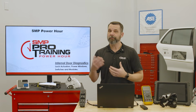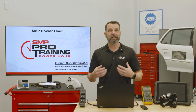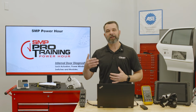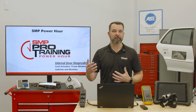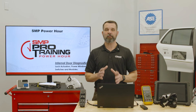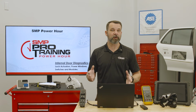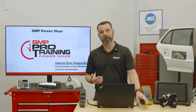And so in summary, modern vehicles rely on a network of switches, motors, and modules, and the BCM to operate something as simple as a window or a door lock. And when we're diagnosing these systems, we need to think logically. Did the BCM get the command? Did it send the command? Did the motor receive power? And is the mechanical part working? Because most of these components typically fail in very predictable ways, and with a structured approach, you can diagnose them pretty quickly and pretty confidently most of the time.